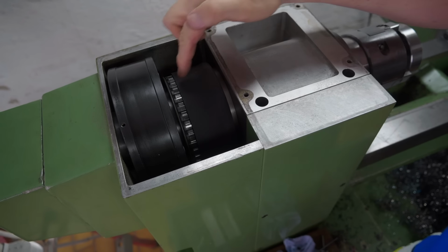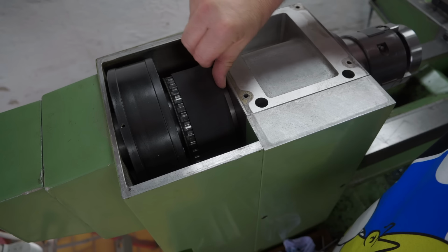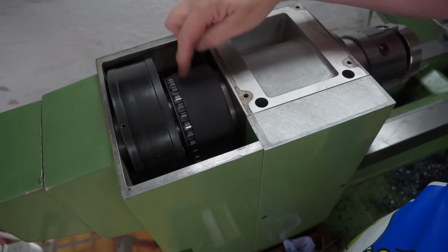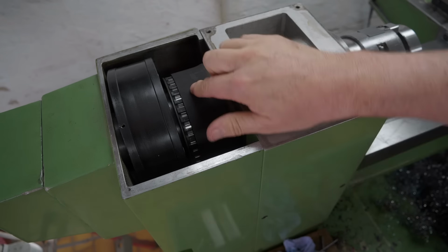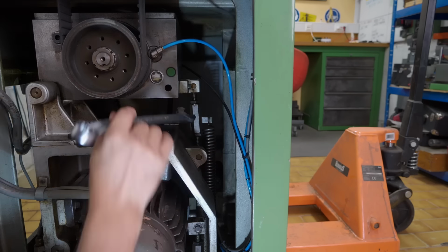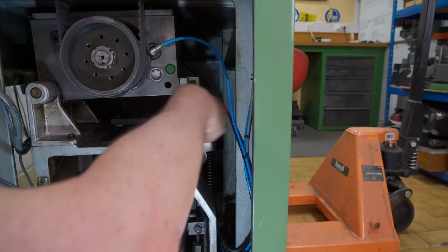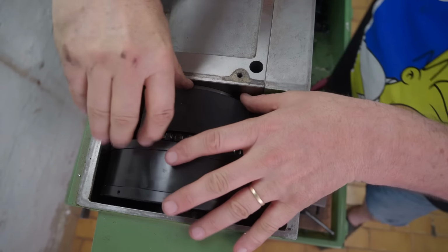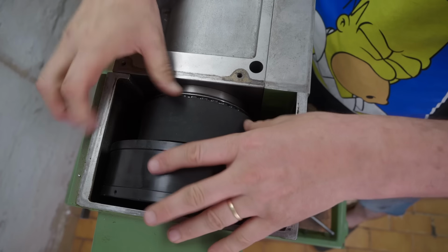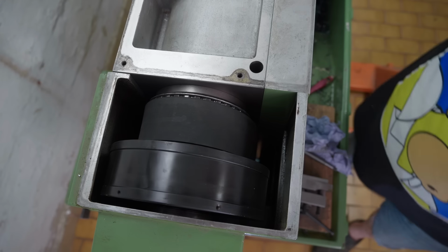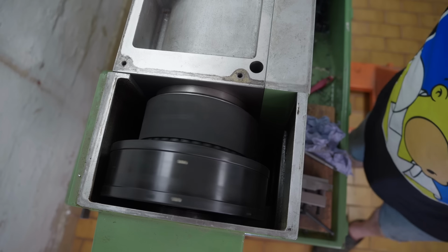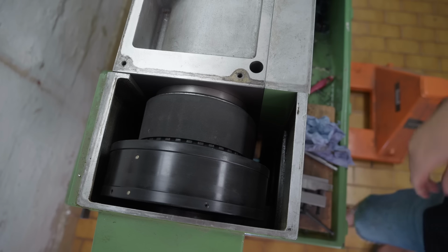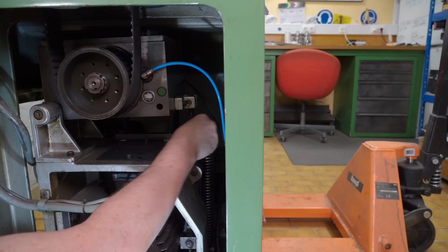First glance, that's not good. This belt has ridden up over the edge of the toothed drive pulley. I'll have to release the tension on that. Yeah, let's crank up that whole motor unit. I wonder if that alone was the problem. Right, that all feels smoother.